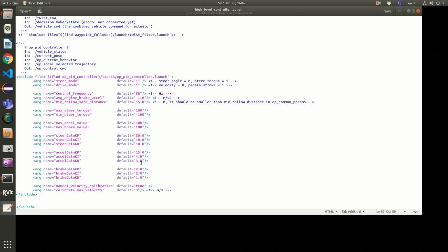You start with initial parameters and check if you have overshooting. Maybe the D component or the P component has the problem. If you are not reaching the target point, maybe your integral part is too small. If you are oscillating, maybe the P component is too big, or the D component is too big. If you have experience with control theory, you can understand more deeply why your parameter values cause this kind of output behavior.